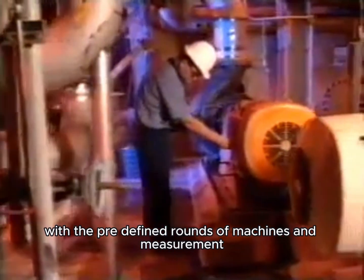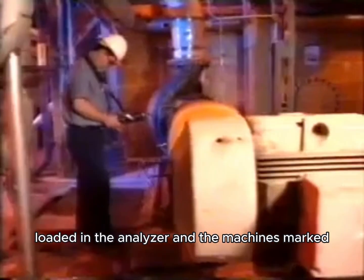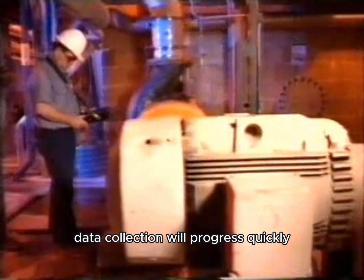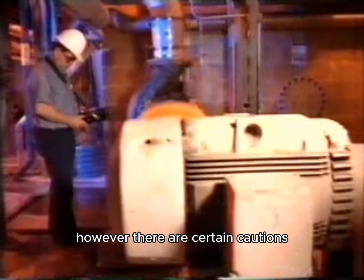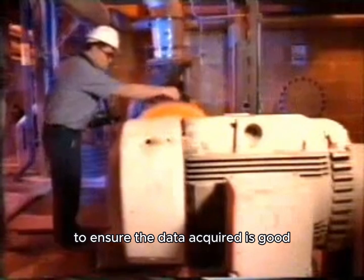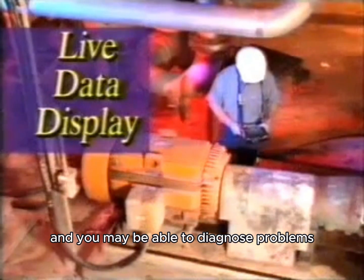With the predefined routes of machines and measurement loaded in the analyzer and the machines marked, data collection will progress quickly. However, there are certain cautions and considerations that should be made to ensure the data acquired is good. The first consideration is to view the data live as it is collected. This will allow you to make a quick check that the data looks reasonable, and you may be able to diagnose problems as you collect the data.